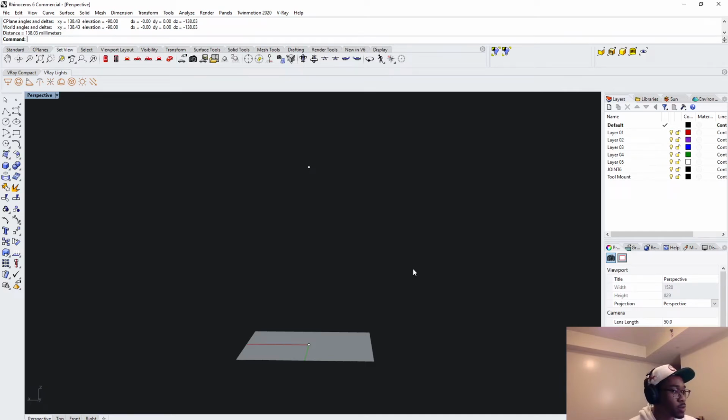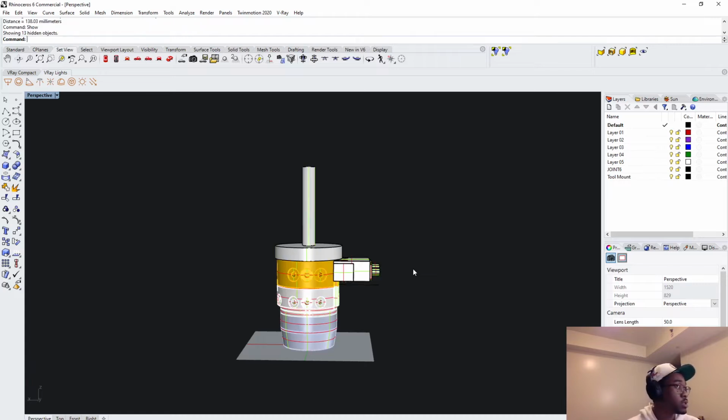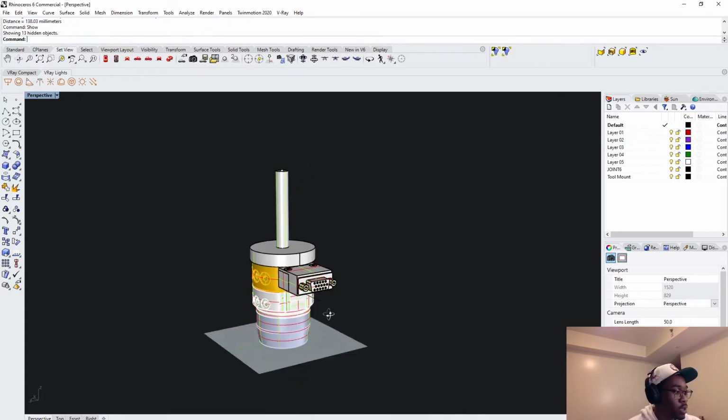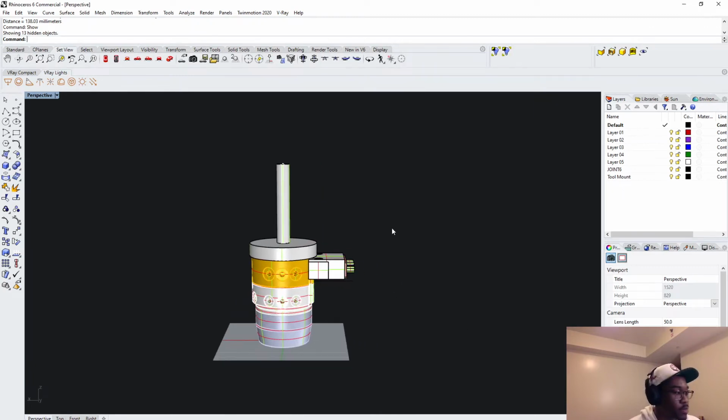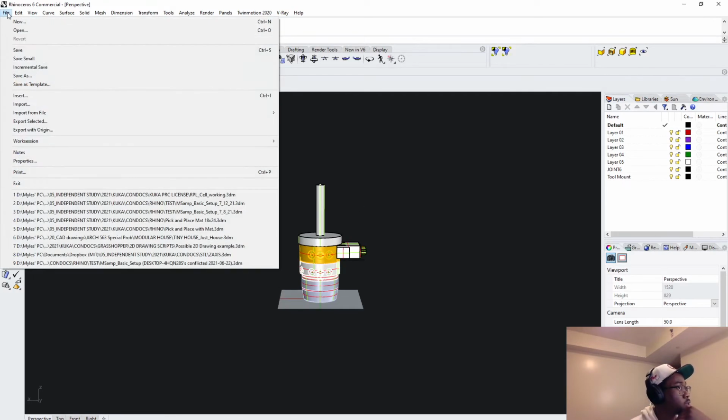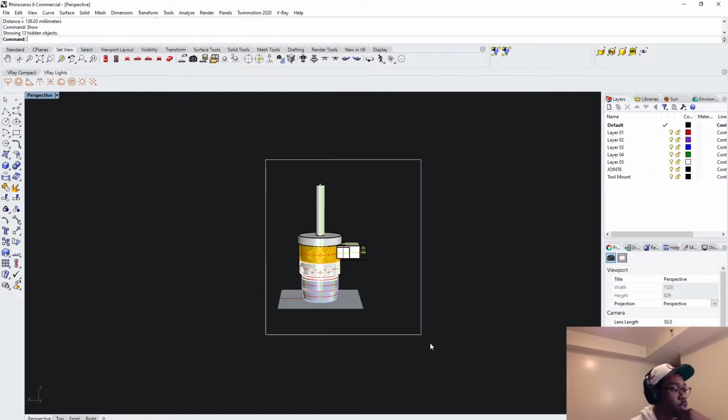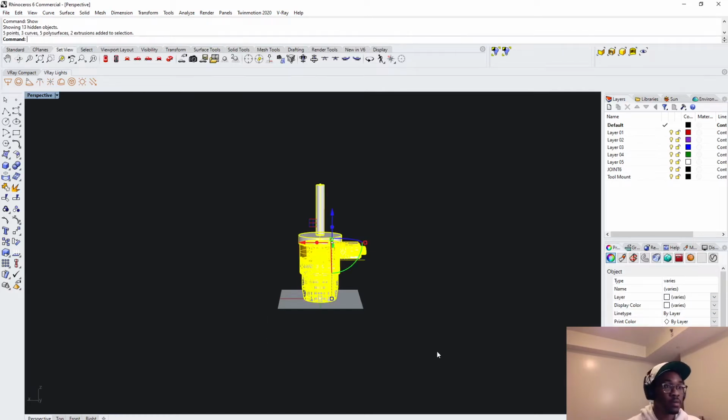What we can do now is record that for later. So now we have a custom tool set up. We know that it's 138 millimeters, and we can now put this into our simulation. So I'm going to show this and pull it up. So the next step, we need to mesh it, and once we mesh it, we need to join it for our simulation. So I will save this. Actually, let's mesh it now just to be safe.